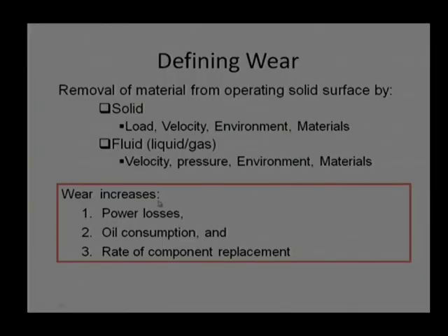Now, this block says wear increases, but before that I can add this: wear is never a catastrophic failure. We will never get immediate failure due to wear. Immediate failure will be because of some other reason. Wear is gradual, it is more like our life.